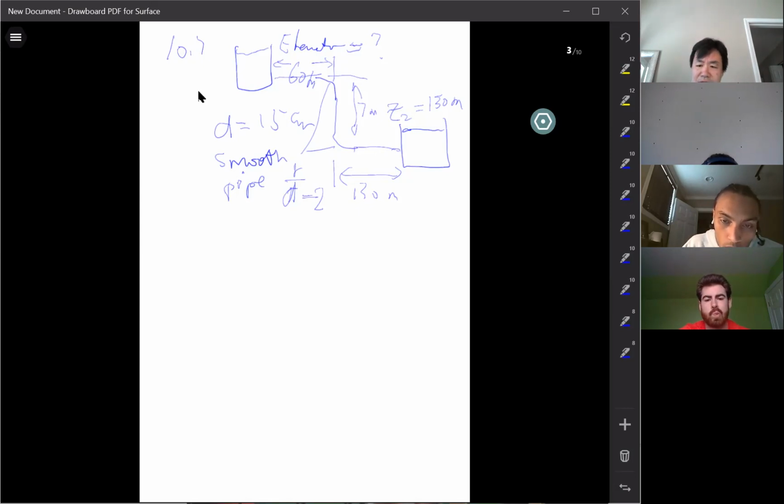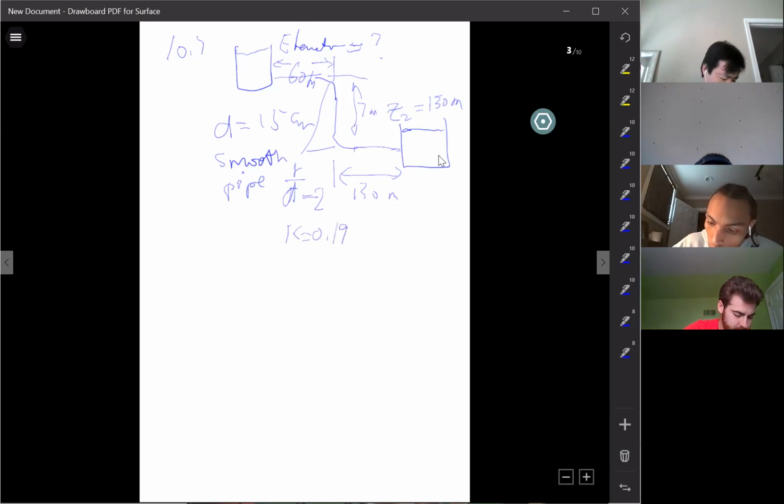Did you see that table on your phone? Look at the drawing there. 90-degree smooth bend. Did you see that picture, where it says R over D? To the left there's a diagram, right? Did you see R in the diagram? So that's the definition for R. D is just the diameter of the pipe. Based on this R and D, in this case R over D is 2, it's given. So what is the K value for those two bends? 0.19. That's right. That's just to test you on how to read this table.